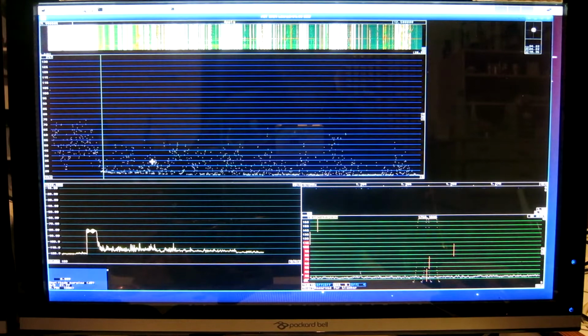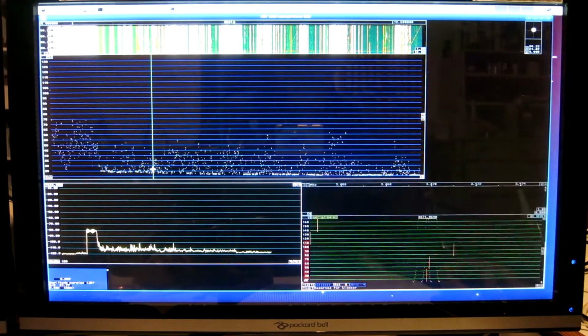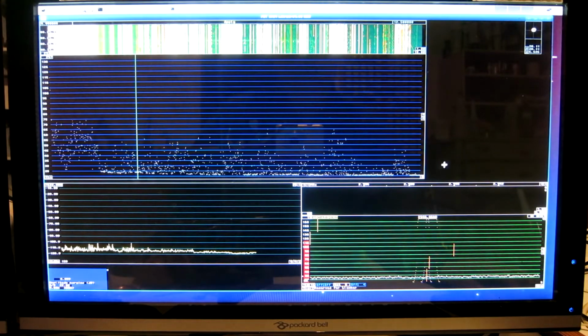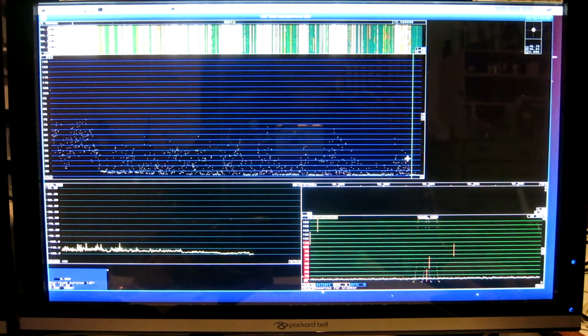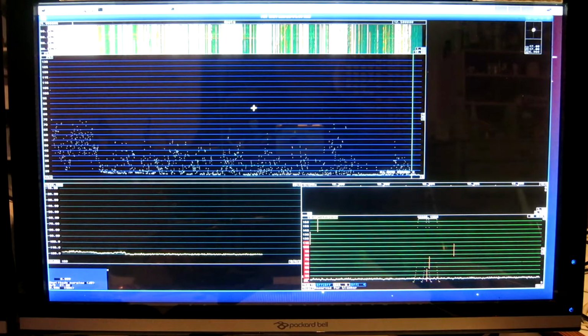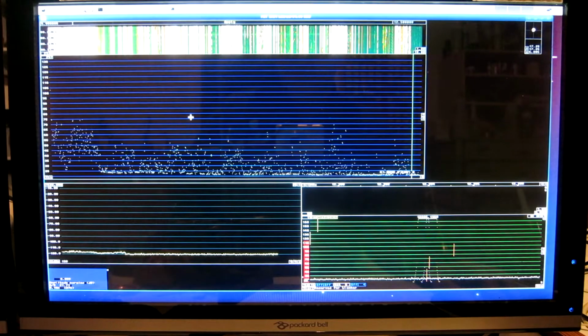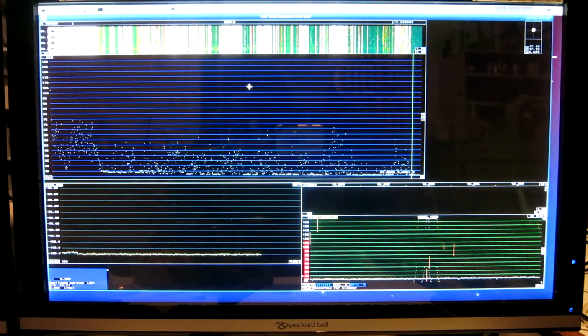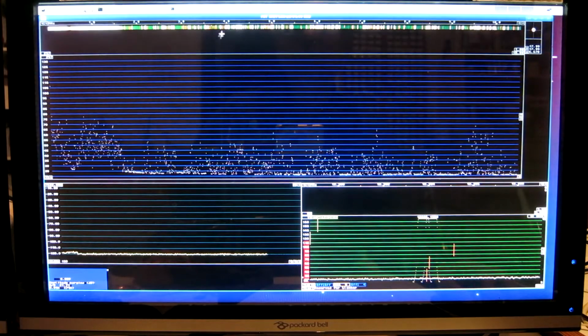And then with increasing gain here, already here maybe 10 dB and maybe 15 dB at the high end. Linrad is not up to this yet. The first FFT is the bottleneck. It cannot do more than 12.5 megahertz, and when doing 12.5 megahertz, it is a compromise.